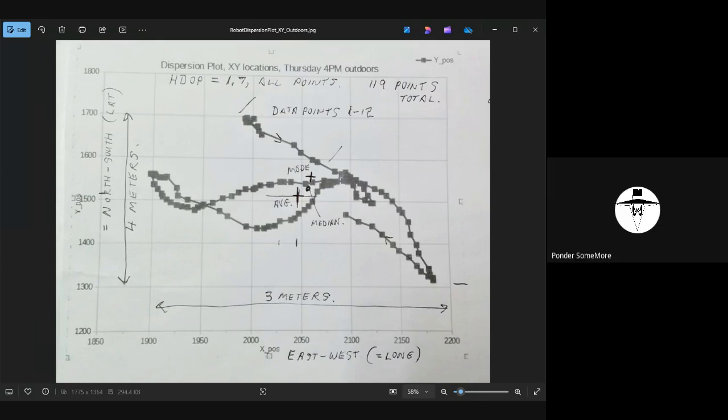Yeah, but that's true for any GPS receiver. It's still going to add more noise, right? And timing. What you basically get from ground bounce is a timing fluctuation as well. Right. So a ground plane's always going to help. It's not going to be that obvious that it's helping in something where you've already got a 3 meter spread. Right. So you may simply just notice it more, but I've also got 2 centimeter accuracy without a ground plane on RTK. It's completely possible. It's just better to isolate yourself from those variants.